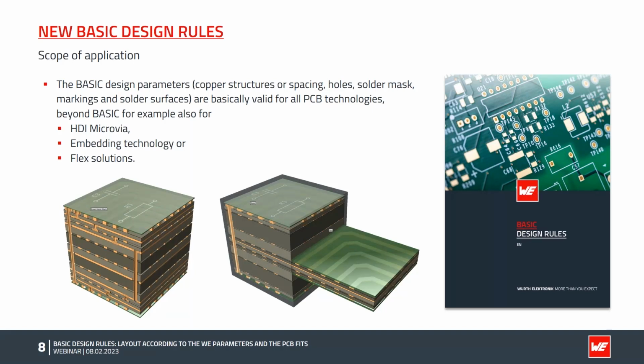So as you can see here on these stack up pictures, of course, this shows an HDI stack up with several microvia layers, and so as well we have solder mask, we have outer layers, we have inner layers, we have plated through holes. So for all these aspects which are described in the basic design rules, this also fits for HDI microvia. But of course, additional design rules have to be added, covering the special technology issues for maybe HDI microvia, embedding, or flex solutions.